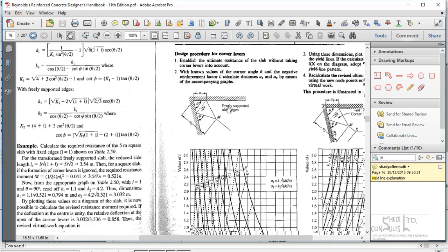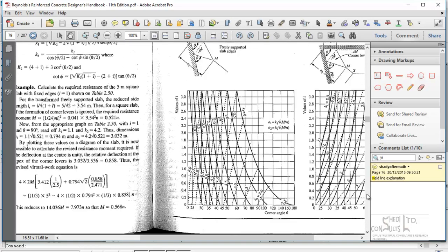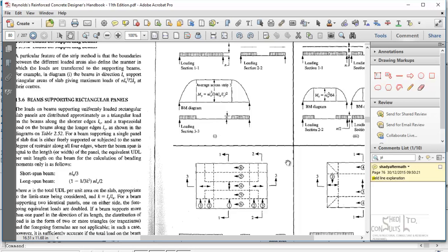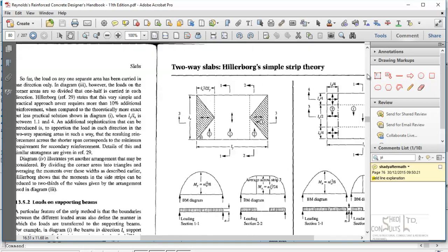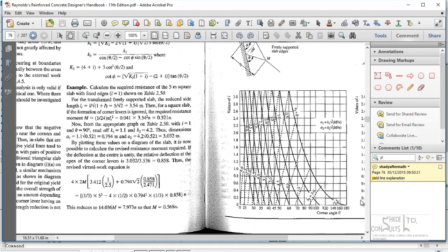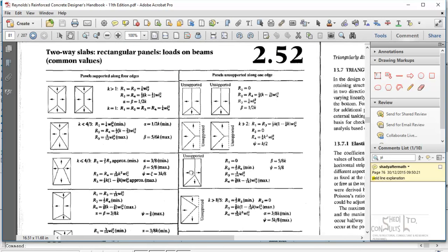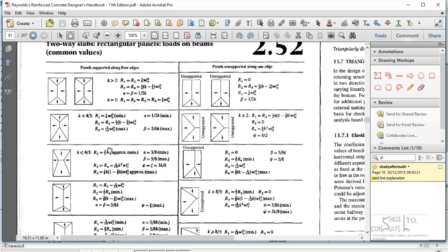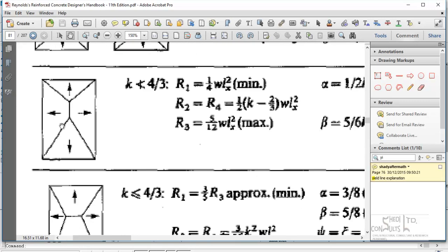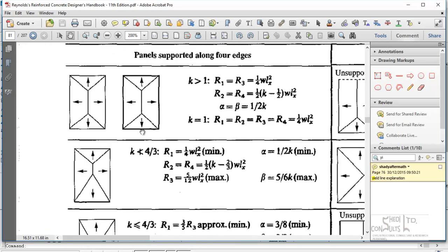And it's on those yield lines that define how the loads will be transferred onto the beams that adjoin or form the boundary of the slab panel. If you look at this yield line formation, if you have all the slab edges continuous, yield lines form at the intersection between them.